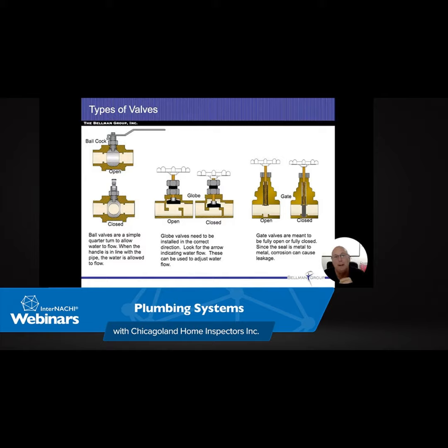Fallen baffles, we should see them hanging at the very top, right through the draft hood. If those little hangers break off and this falls to the bottom, it usually disrupts the flame and it might damage the burners. Those burners underneath there are flimsy. They don't have any strength to it. So if something comes down and gives it a good whack, then it knocks it out of alignment pretty quick and easy.